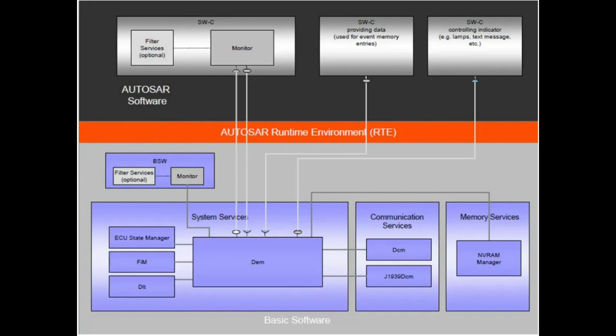So they are going to monitor the DEM events. I said it is now related to voltage. When the supply voltage is less than 9 volts, the DEM will log it, and that monitor should be taken care of by the COM. When the supply voltage is more than 16 volts, then a high voltage event should appear. That kind of monitor is in the COM. Similarly, based on all these requirements, they will log the DEM events.